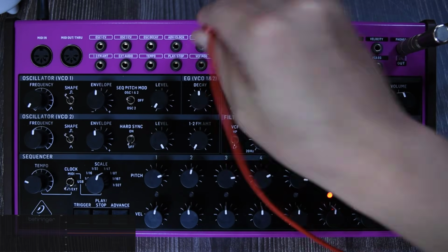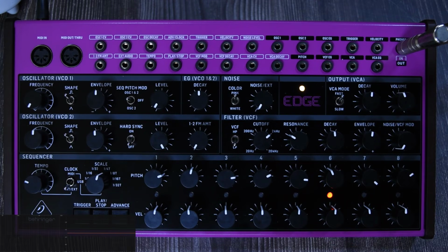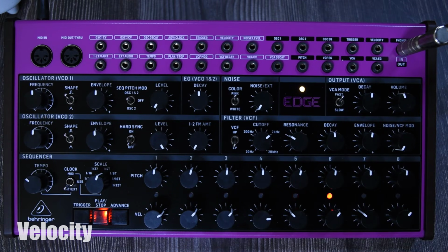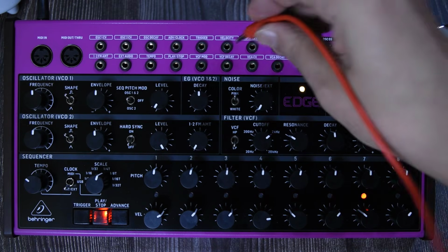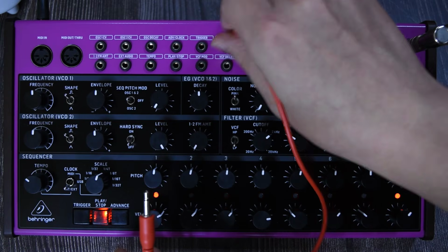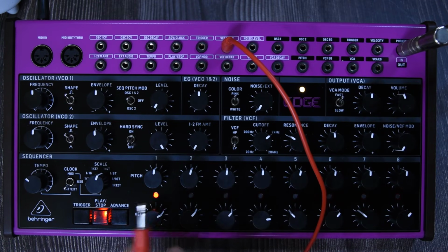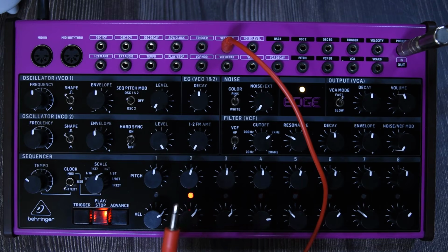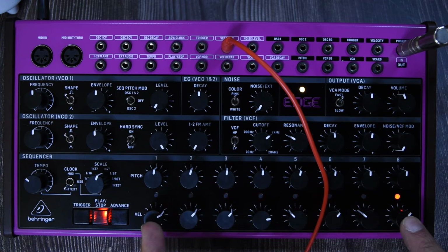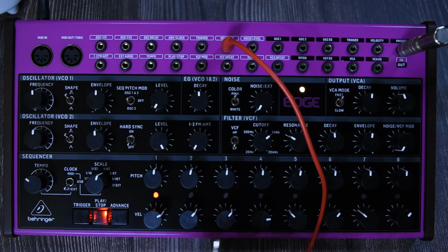Well, let me just disconnect it. So this trigger in is going to take from 0 to 5 volts. It could be a pulse or it could be a gate signal. Now right here we have the velocity in. If I play it back, we know that these knobs are going to make it go up and down in volume. As soon as I connect something, I'm going to make sure that I keep the other end right here, and I'm going to be connecting something. As soon as I do so, the sequence is still going, but we get nothing. We get no sound. And it's because when we connect something to the velocity in, it's going to sever or disconnect whatever these knobs do. And remember, they are in charge of controlling the amplitude.